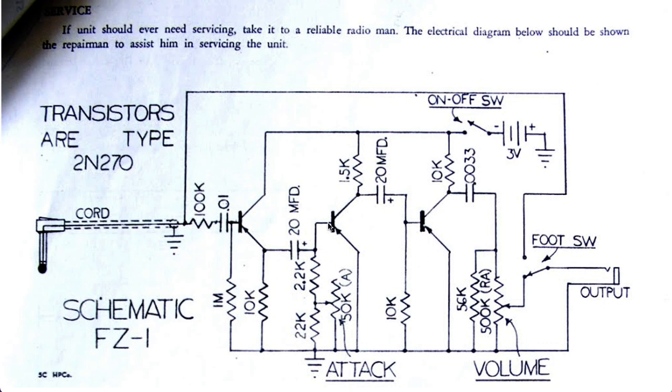In this lecture, I'll look at a direct coupled example that's more difficult to analyze in terms of the biasing. But looking at the individual stages, notice that the first stage is an emitter follower. It's a common collector stage. So this first stage is acting as a buffer. The next 2 stages are common emitter stages that are providing gain, and each of those is inverting, so the total structure is non-inverting.